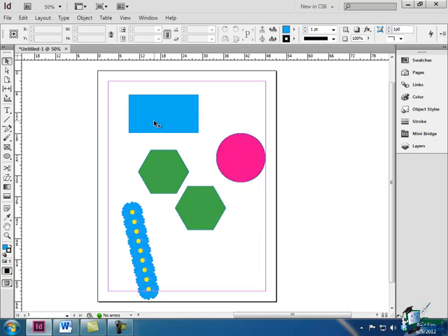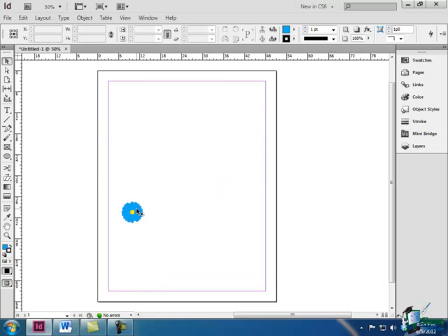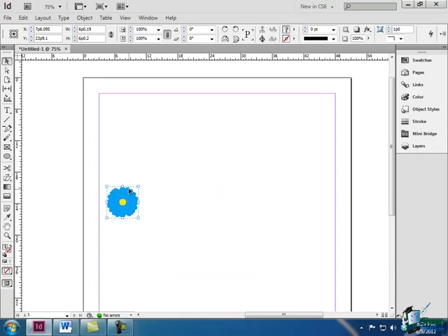To demonstrate, I'm going to remove some of the items on our document. Next, I will select the object. Then, using the Selection tool, hold down Alt on a PC or Opt on a Mac and start dragging. While dragging, release the Alt or Opt key. Press the left or right arrows to change the number of columns.